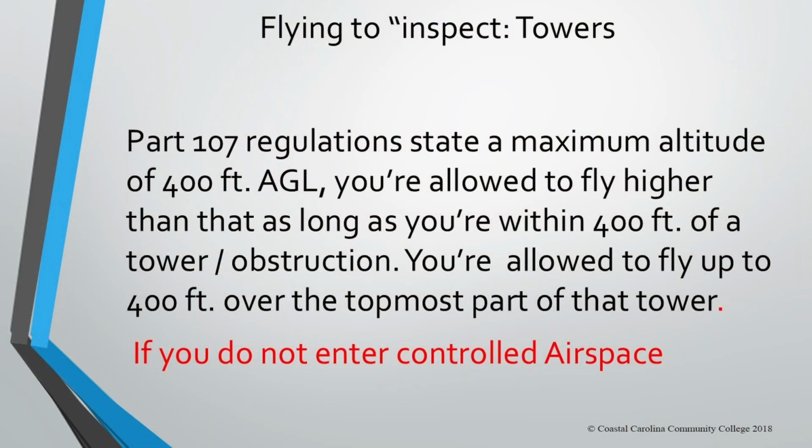Altitude, you cannot exceed 400 feet above ground level. If flown within a 400-foot radius of a structure, then it can be flown higher, but no higher than 400 feet above the structure's immediate uppermost elevation.